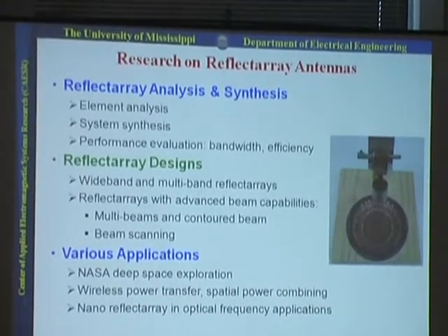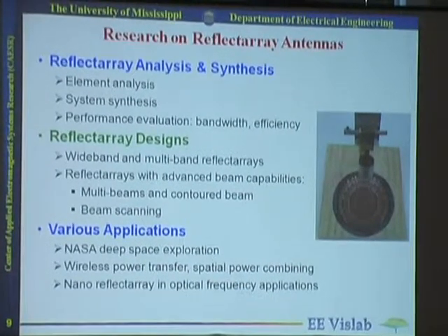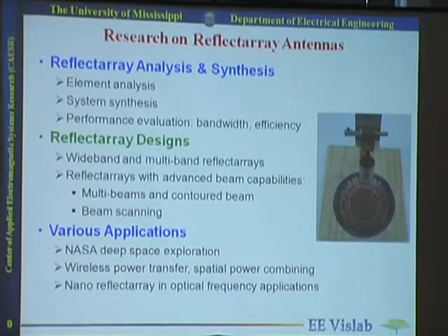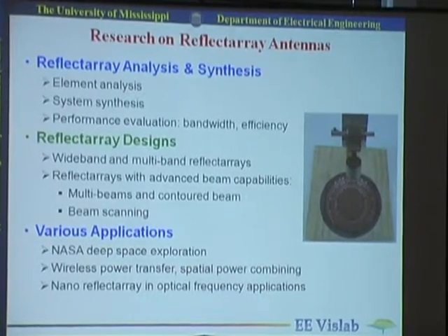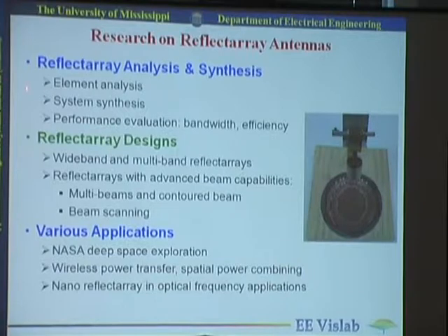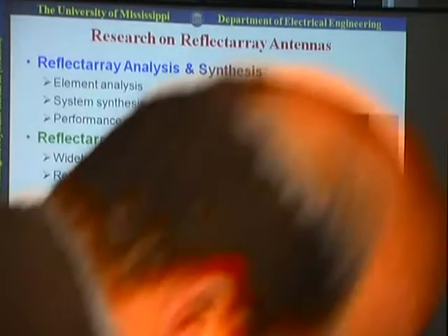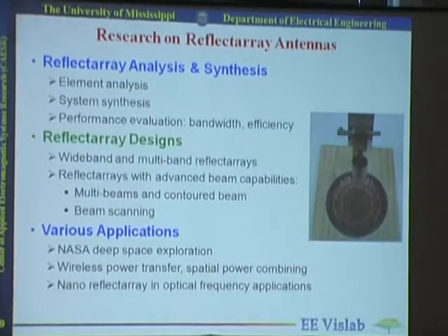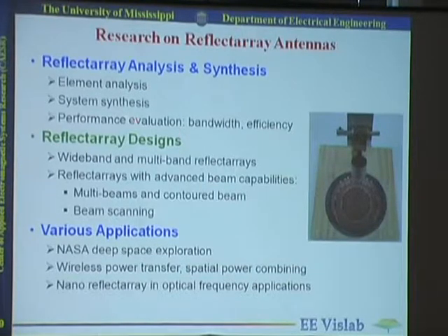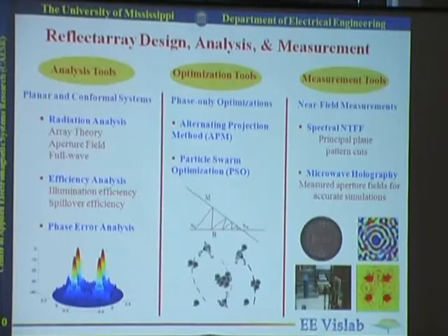So how do we analyze this? I'm going to go quickly, and I intended not to bring so many equations here, but the procedure for analysis, design, and verification is sketched out here in certain items that we have to follow. The most important item is the element analysis, and when you look at this shape here, it's basically constructed from small elements. We do some synthesis for this element, and after we decide which element to use, we're going to start designing the reflectarray itself as a whole unit, and then we test it and verify the design.